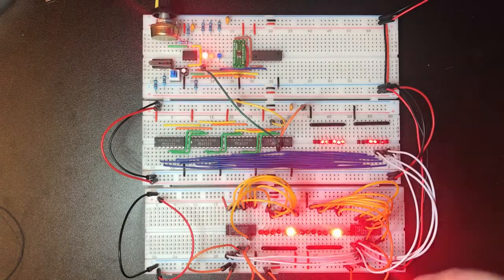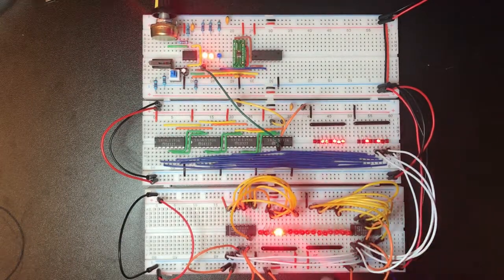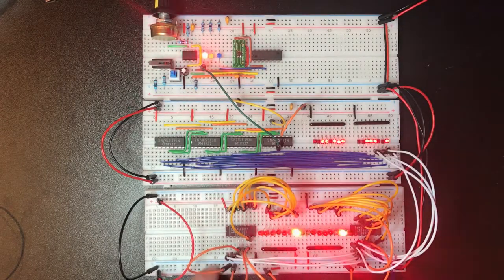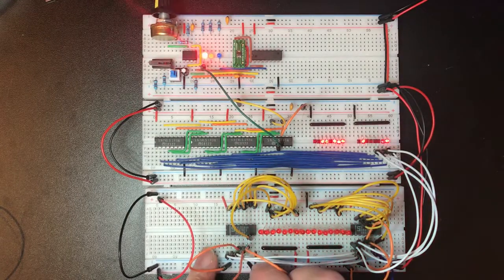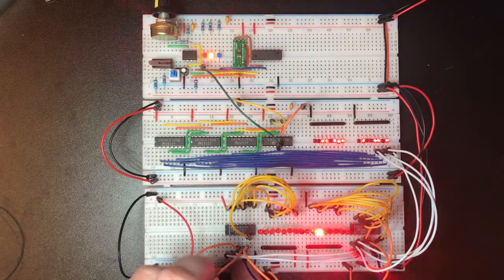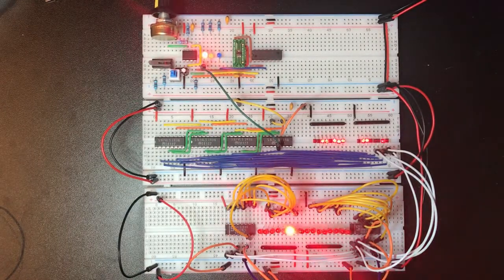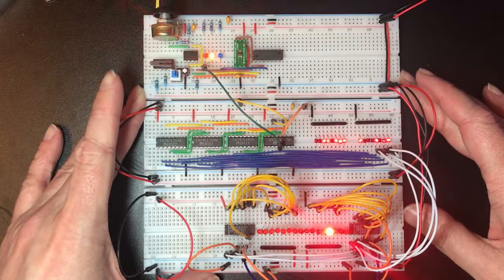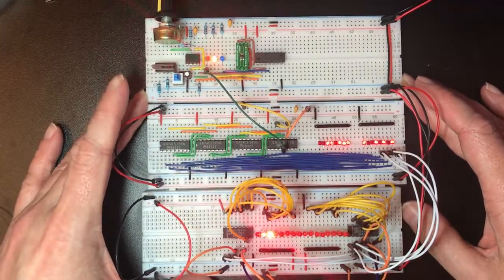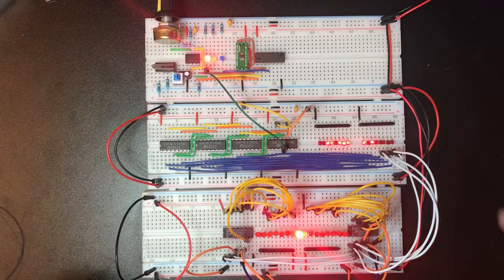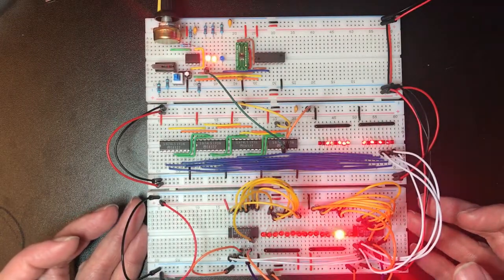So you can probably follow exactly what I'm going to do here. I can then daisy chain that on to one of the active low inputs on this second chip, and now what we get is our selection is seamlessly extended up to 16 lines without the need of any additional ICs. So that's really cool. I'm actually pretty happy with this, and I can see quite a lot of uses for this configuration in the CPU design.